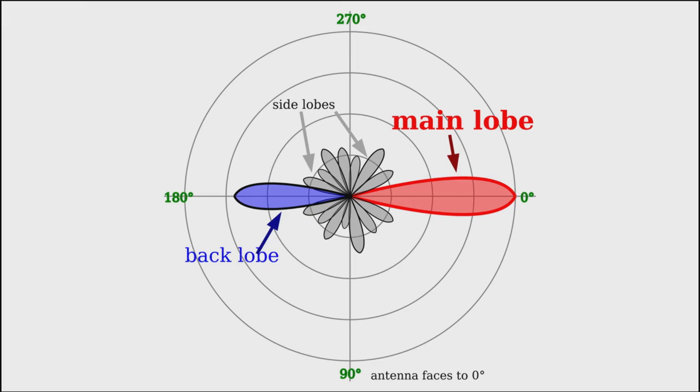Now, this picture that I'm showing here really is not demonstrating near field and far field, but we can use it for that. So that's what near field is. Anything close in can affect the pattern. But as you get out farther, it doesn't. So the far field is a region in which the field is settled into normal electromagnetic radiation. In this region, it's dominated by transverse electric or magnetic fields with electric dipole characteristics. In the far field of an antenna, radiated power decreases as the square of distance, and absorption of the radiation does not feed back to the transmitter.